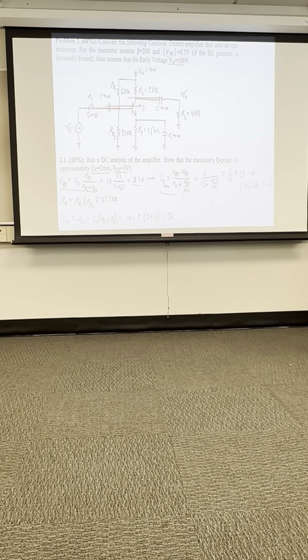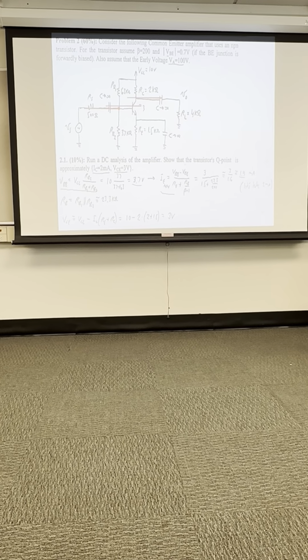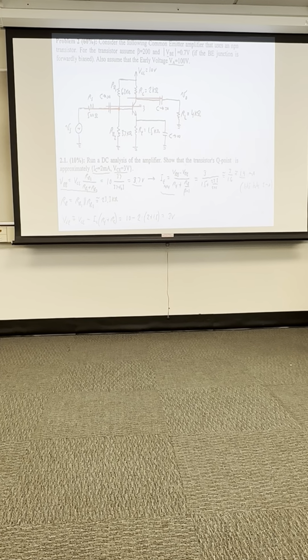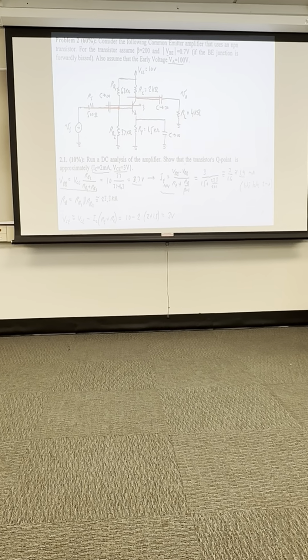And then we would get a different voltage on the base right here, because now we have base current, and now we have to resolve for I sub E. So the preference here is just to assume alpha is equal to 1. If the design specifies that you need to calculate I sub E based on beta, then that's what you would do. If the problem does not specifically indicate that, then I would just say go with alpha approximately equal to 1. Thank you.